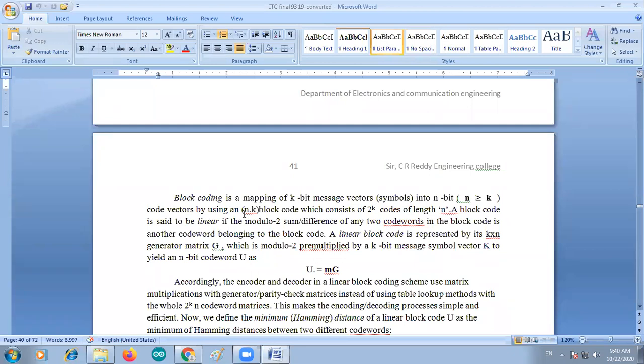That is the encoding technique involved to convert 8 vectors into 128 vectors. So of the 128 vectors, 8 are the valid code words, because the message vectors are only 8. That's why the 8 are the valid code words. The remaining vectors are not valid code words. You can identify how many valid code words there are by the decoding process. Later we can go for the decoding process.